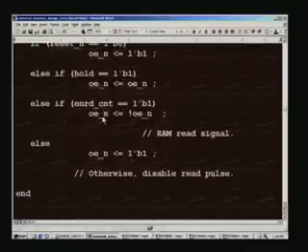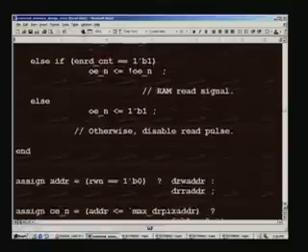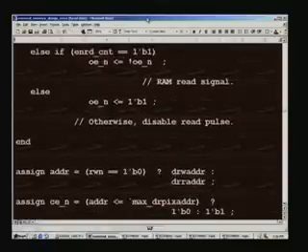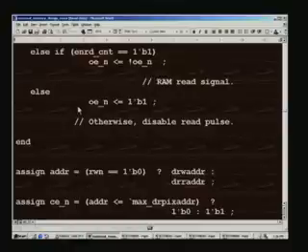This is on similar lines as the write, it is precisely similar meaning here, and otherwise we take the read to the inactive state. By this means we can have a true random access, in the sense that we can change address and change from read to write, and vice versa.